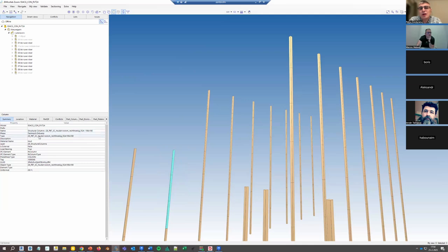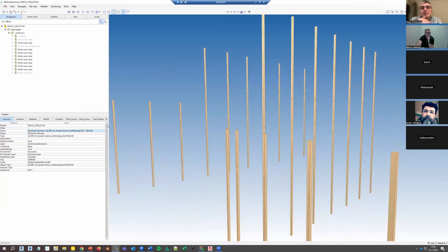Sorry if I caught you off guard and if you did not spot this problem before. This is all the same type. Yeah, but when you export this to IFC, does this come out correctly, or do you get multiple types? Because that's why we have an IFC patch in Bonsai, which is called remove duplicate types from Revit. That's cool. We could see what happens.